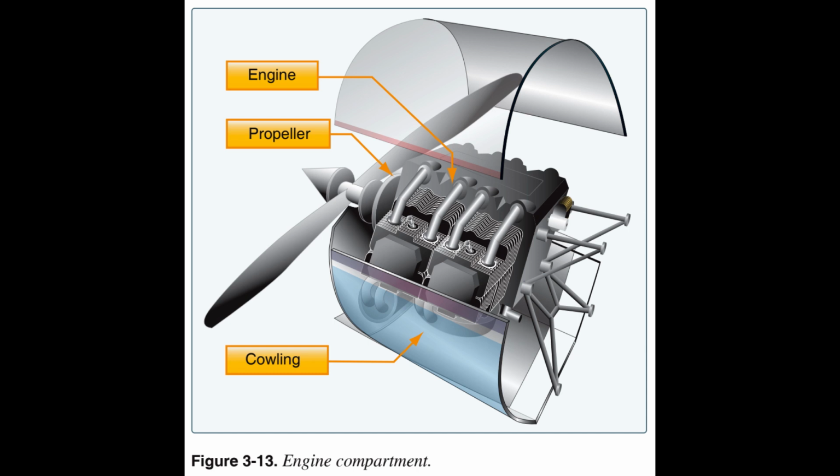The primary function of an aircraft electrical system is to generate, regulate, and distribute electrical power throughout the aircraft. There are several different power sources on aircraft to power the aircraft electrical systems. These power sources include engine-driven alternating current, AC, generators, auxiliary power units, APUs, and external power. The aircraft's electrical power system is used to operate the flight instruments, essential systems such as anti-icing, and passenger services such as cabin lighting.